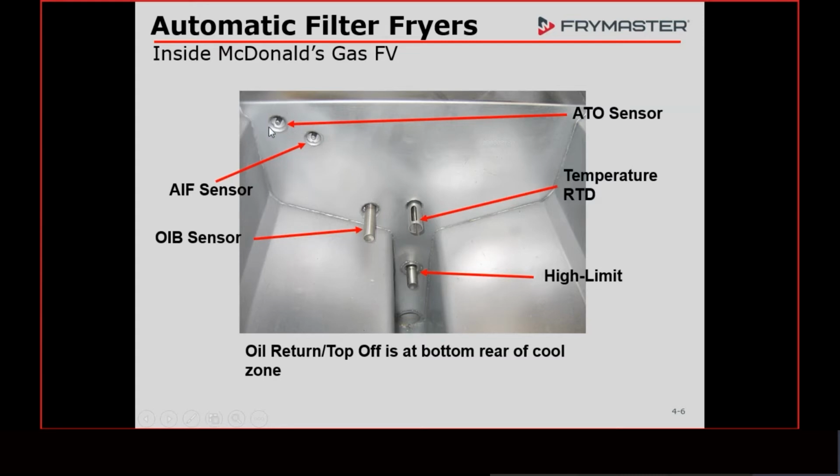That's good information, considering if you've got all three probes in the same oil, they should all be very close in temperature. If you've got one that's way off, but it's physically in the same oil, even though it may be a little bit warmer in certain regions, this should be pretty uniform. We shouldn't be too far out of whack, because 5 degrees is the trigger for the top off system once it sees 5 degrees. So we have to make sure that the oil is pretty uniform, and when we check these, we need to make sure that we're definitely within plus or minus 5 degrees.